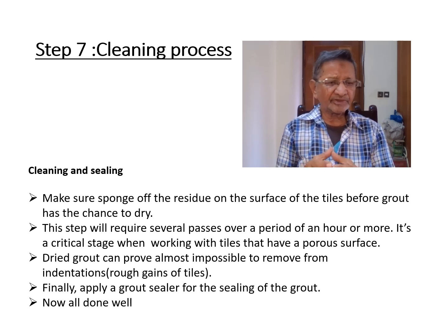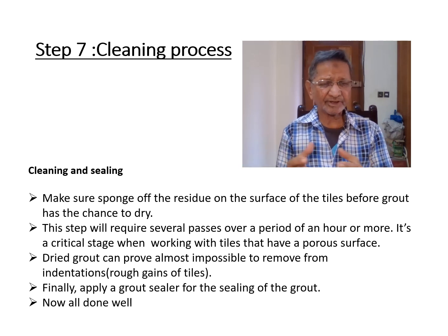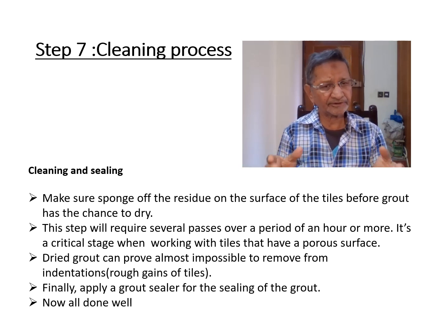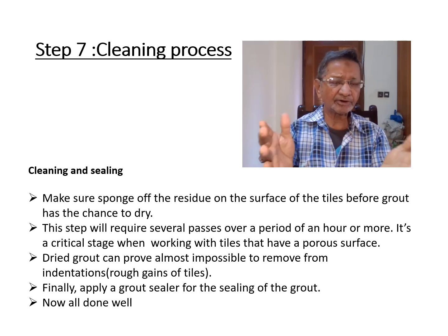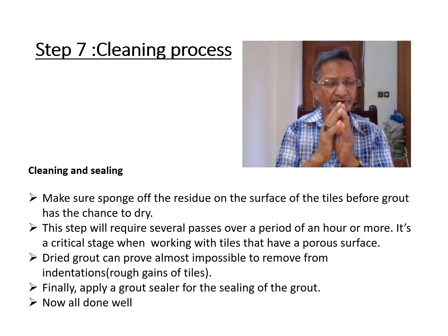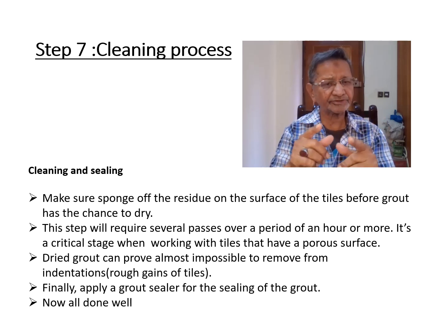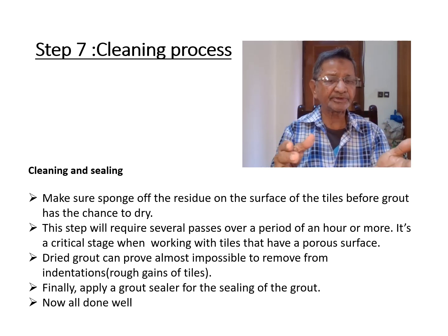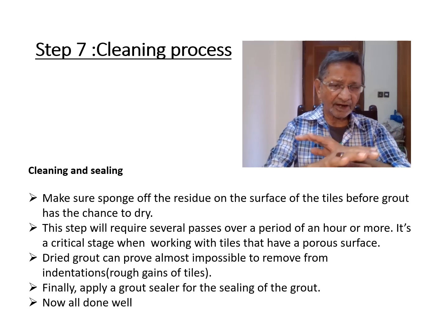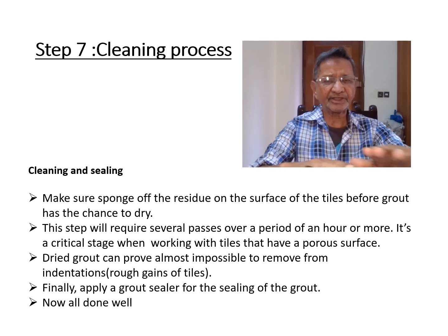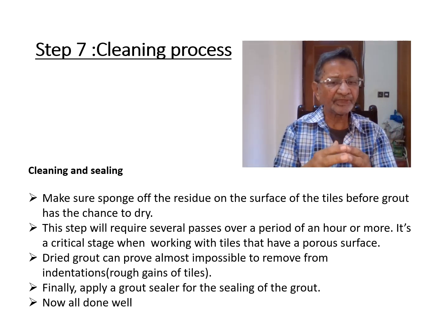Dear viewers, now we are in slide number 7 where the final stages of the installation of tile are to be discussed. Earlier we discussed the layout of the tile, then installation of the tile, then the adhesive to be applied, how the adhesive is to be applied and what care is to be taken, then grouting of the tiles is to be done. Grouting is done in such a way that the grout is spread and then cleaned from the surface.